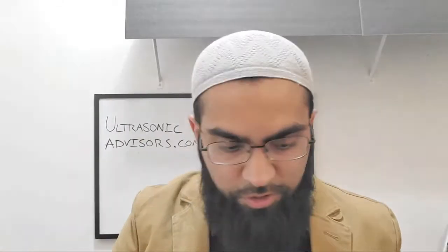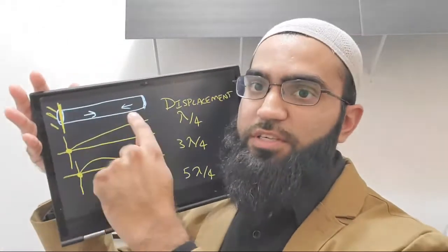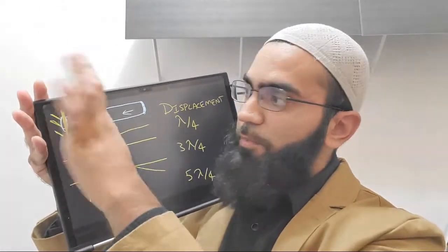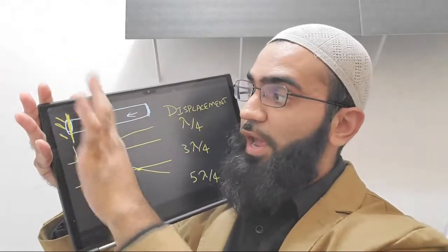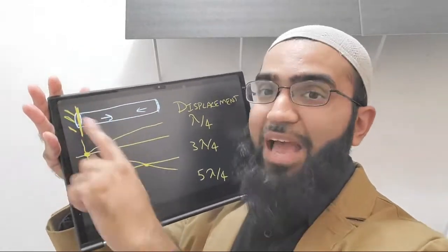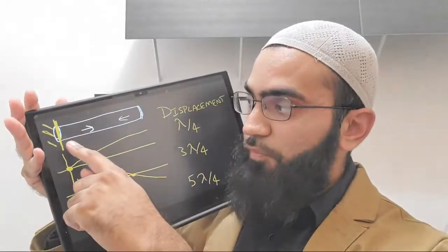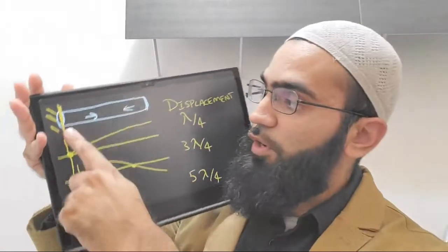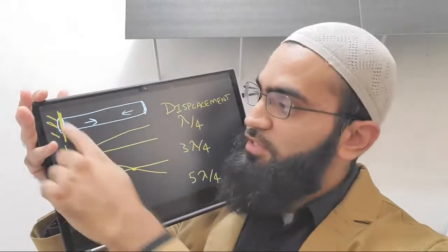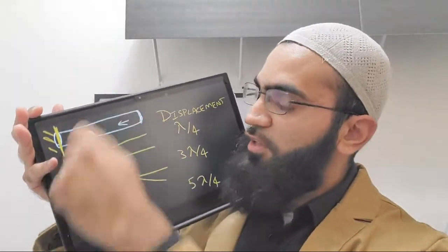You have a stepped horn, whether it has curvature going down to the step, or whether it is simply an abrupt change, that actually closely looks similar to this case, where you have a heavy mass, or a clamped condition. So this is very similar for a stepped horn, or a smooth transitioning horn, where the wavelength is now clamped on one side and free on the other side.